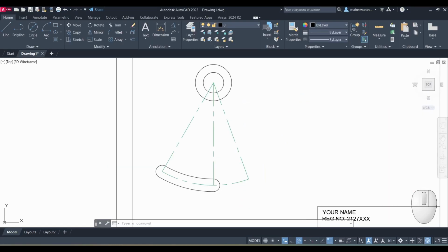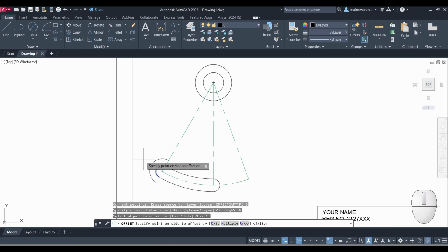So go to AutoCAD, click offset. You can see the offset command here. Click that offset. Once you click, it is asking you the distance. So the distance is 8. Press 8, press enter. Now it is asking which object you have to offset. Click the object. When I move my cursor, you can see, I am moving it out, so you get that particular curve. Click. Again, I want this also. Click, move your cursor outside, click. Like this also, click, move my cursor outside, click. So you will get these arcs. So I think this part is over.